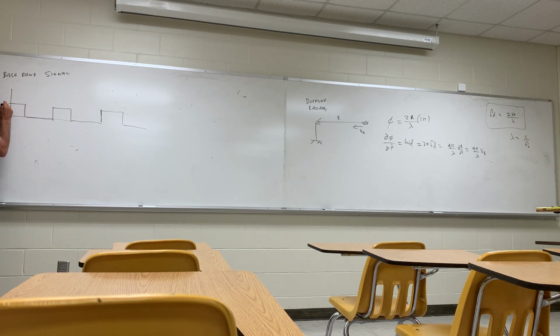It has some amplitude A, and it has an on time, this is the 0 point, that's the origin, of tau, and it has a duration of T, and that's usually called the pulse repetition interval, or PRI, but you're familiar with T as period, aren't you, class? When you've had a lot of your coursework, T just means the time over which it repeats itself. This is the baseband waveform.